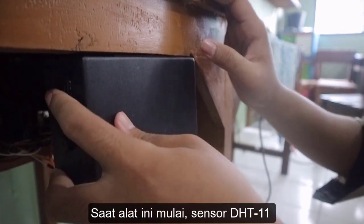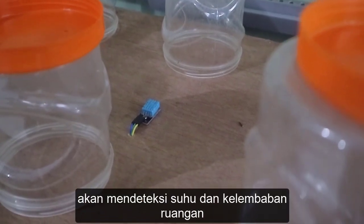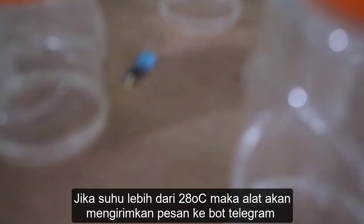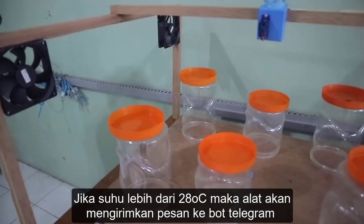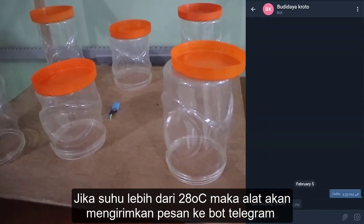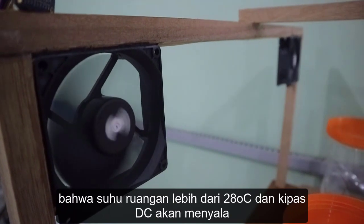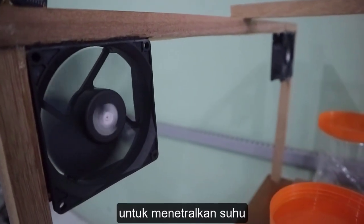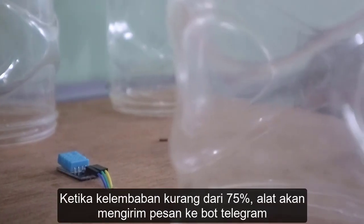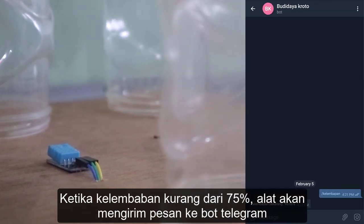When this tool starts, the DHT11 sensor will detect the temperature and humidity of the room. If the temperature is more than 28 degrees Celsius, then it will send a message to the Telegram bot that the room temperature is more than 28 degrees Celsius, and the DC fan will turn on to neutralize the temperature. When the humidity is less than 75%, it will send a message to the Telegram bot.